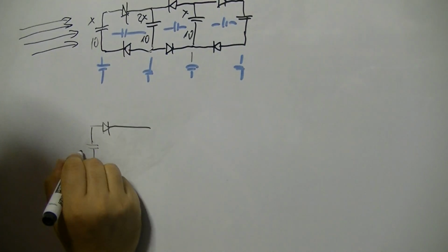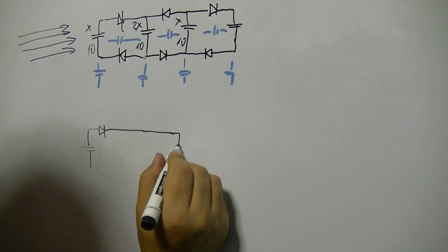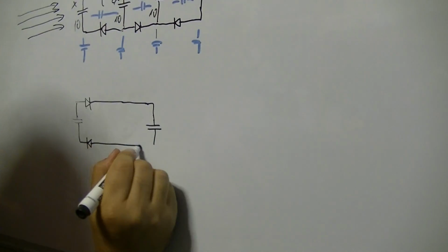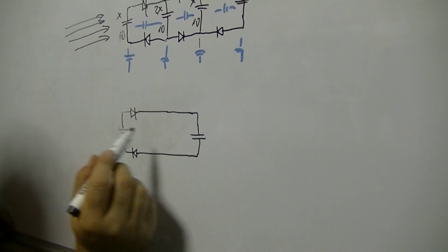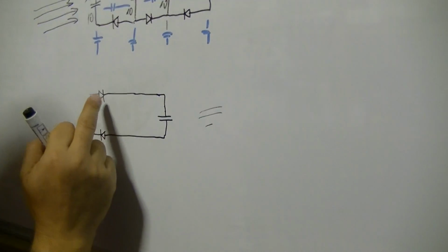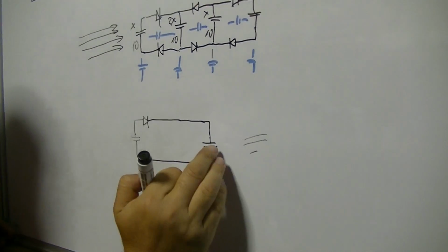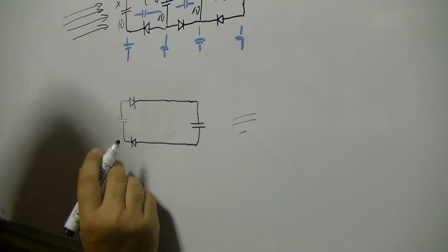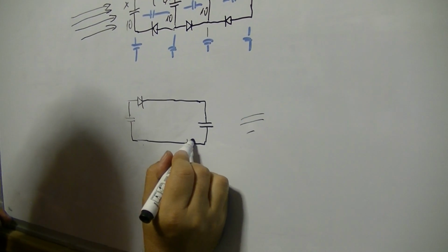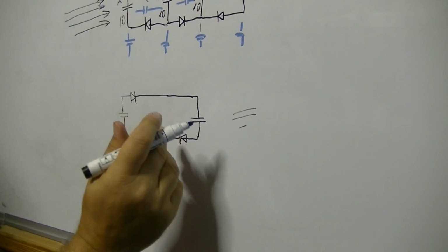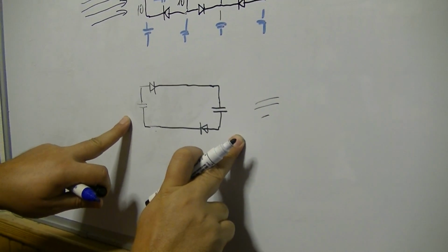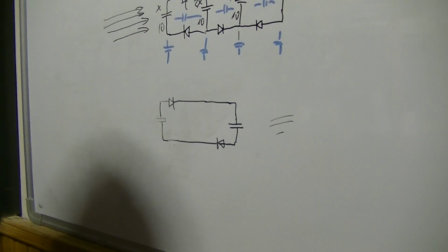What is also very important to say here: the diode is close to this capacitor, and this capacitor is forward, so if radiation comes from this side, it will work like I show. But if radiation comes from this side, when diodes are distant from the receiving capacitor, there will not be charge collection. Also, if diodes are placed one too close to another, again it will not collect anything. It must be like I showed in the beginning.